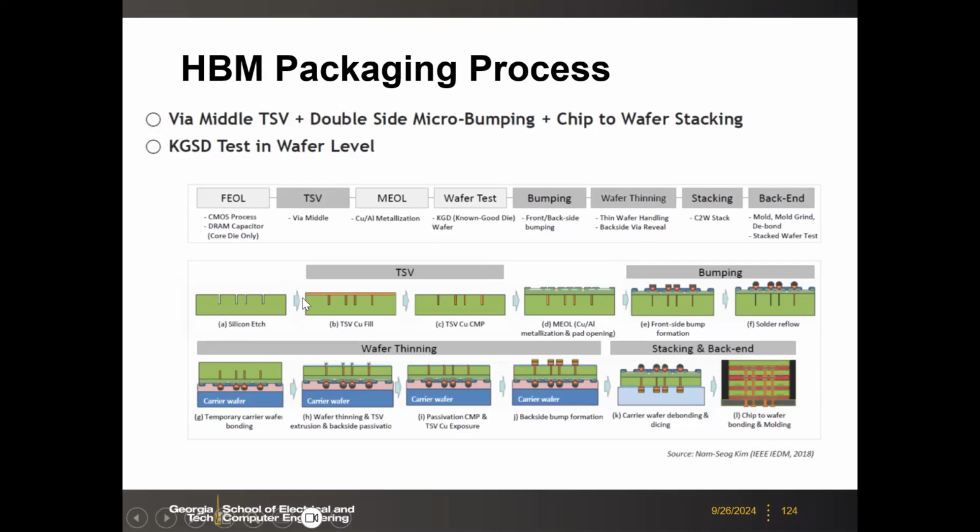Let's say what you are doing here is the single 2D DRAM die fabrication all the way, and then make those bond-ready, and also thin the wafer down, and then expose the backside. Then basically at this point, a 2D DRAM die is ready with those interfaces exposed for the bonding. So you do the bonding vertically by stacking many of those. Okay.